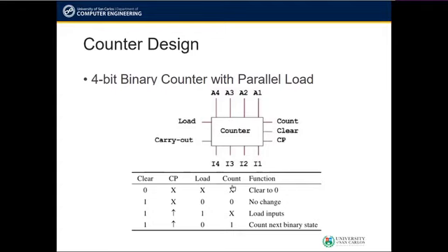This means that the clear pin is active low, or is triggered when an input of logic 0 is inputted to it. So when the input to clear is 1, it does not have any effect on the counter operation, just like the 3 operations here. As you can see, the clear input is 1.